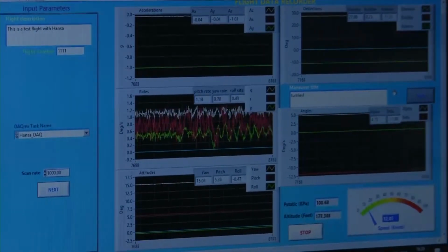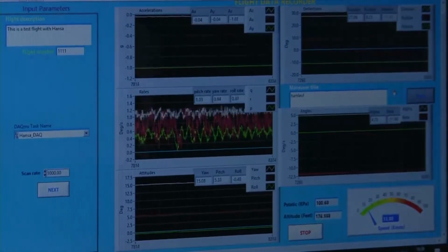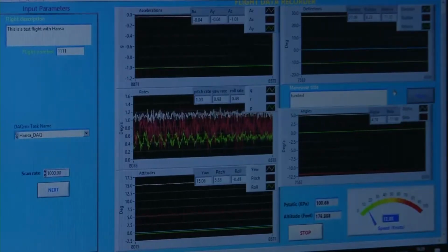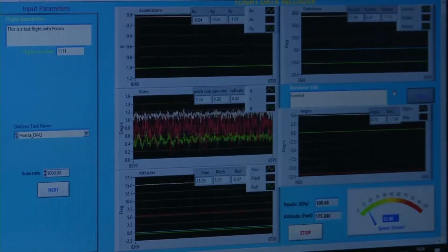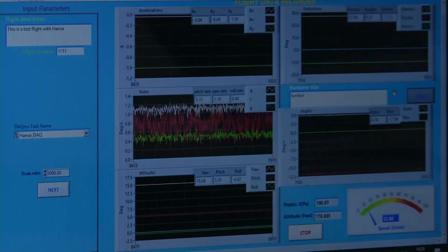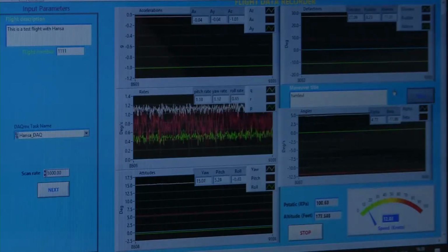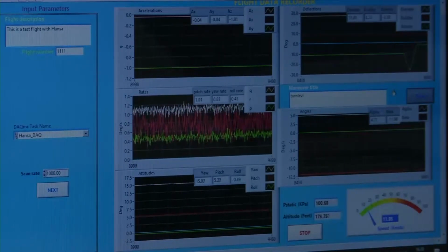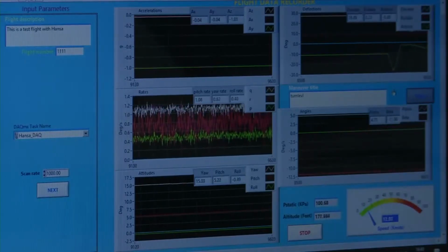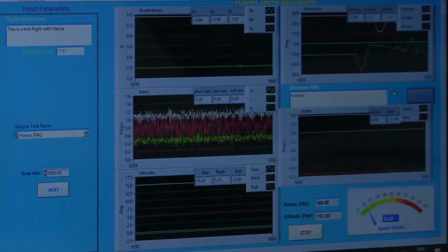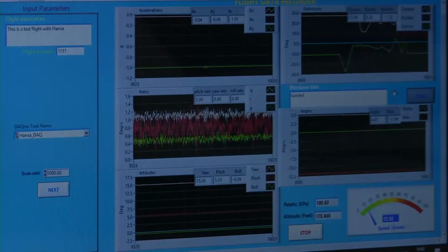Because suppose while you are trying to build an autopilot, you want to have a particular restriction on turn rate and climb rate, and you have limitations such as your servo cannot go beyond a certain limit or certain degrees. You want to design such that the sizing is enough so that your restrictions can be met. So that's why, while performing in manual mode, you have to collect these data, and based on these data you can direct your autopilot to give this much percentage of gain when performing those maneuvers.